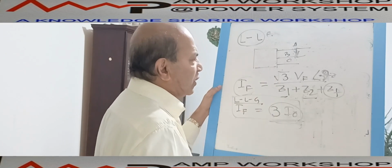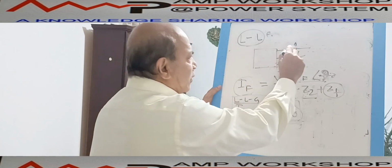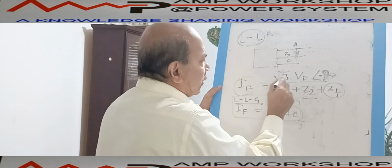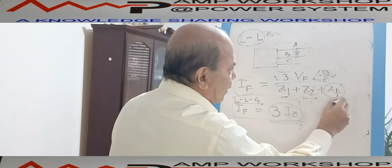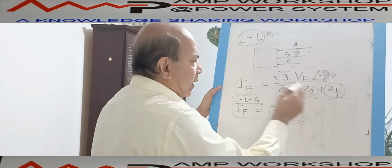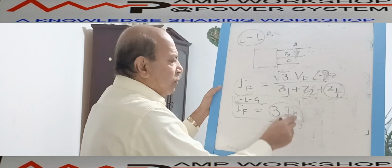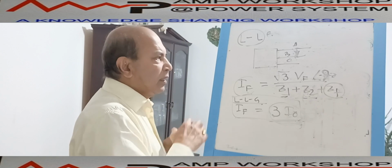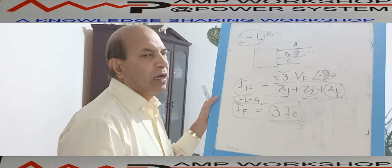I have shown one typical calculation for line to ground fault. If we apply the same way over here, we will get it for line to line fault. The fault current will be root 3 into Vf at an angle of minus 90 degree by Z1 plus Z2 plus Zf. Zf is the fault path impedance and Z1 and Z2 are the positive and negative sequence impedances. And in case of double line to ground fault, Ia is equal to 3 times I0. We can calculate the I0 in the same way as the line to ground fault. So these are the three formulas for calculating the three types of fault current.